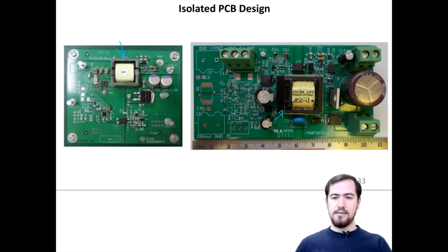However, we are seeing for both of them the optocouplers are placed from primary to secondary side to carry the regulation data from secondary to primary, and we are seeing the isolation barrier distance between these two isolated copper regions.